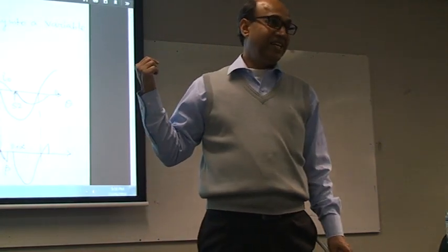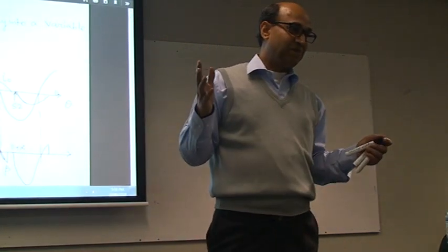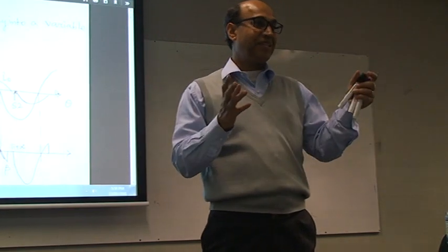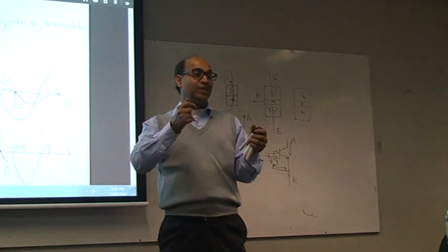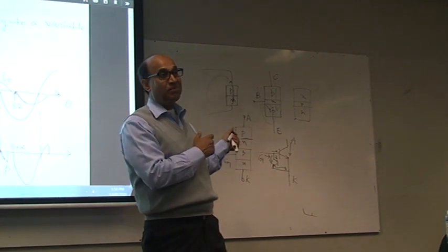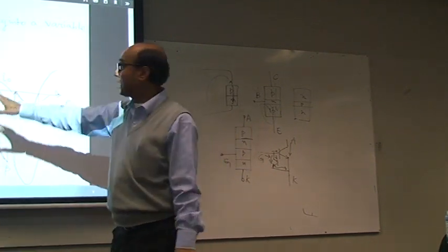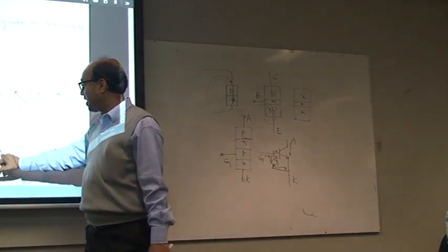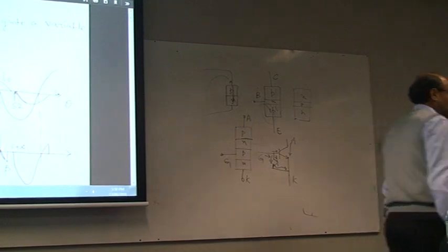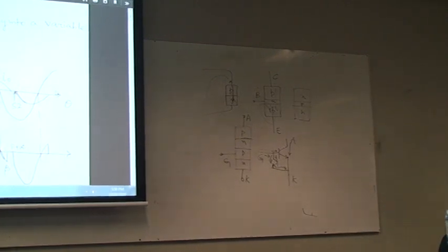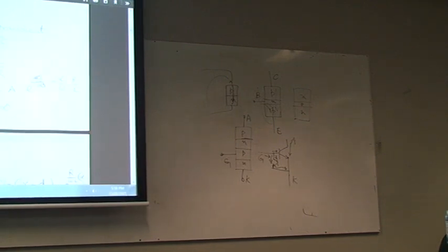But in DC, you cannot switch it off, and you have to make a separate circuit to force the current to 0. That is one of the biggest problems. But for AC, it is okay: if it goes to 0, it naturally switches off. Anyway, we are going too far. So effectively, you can control the power.